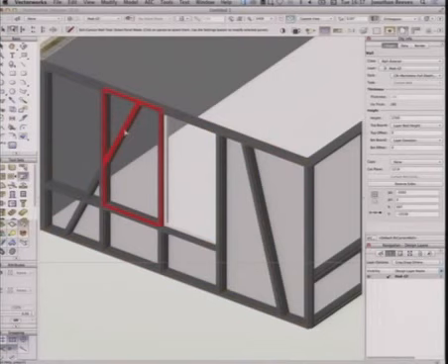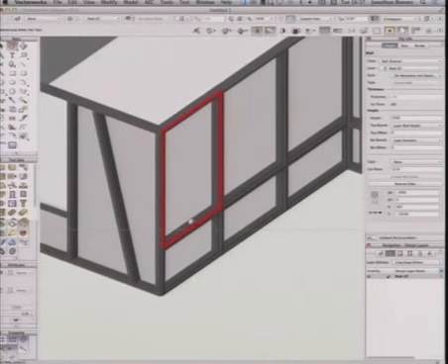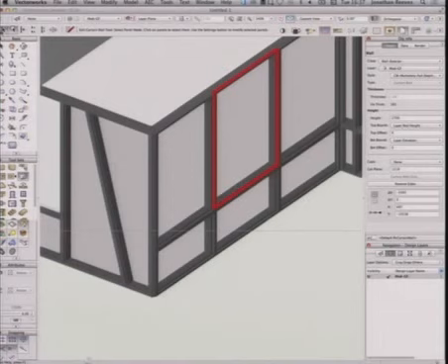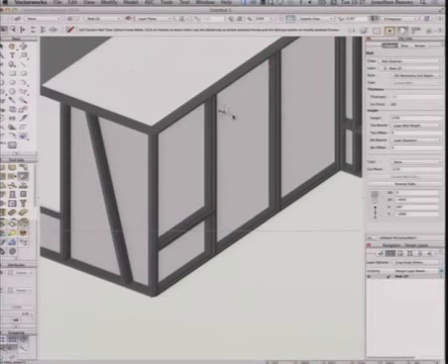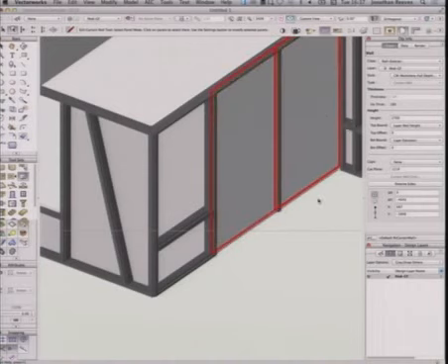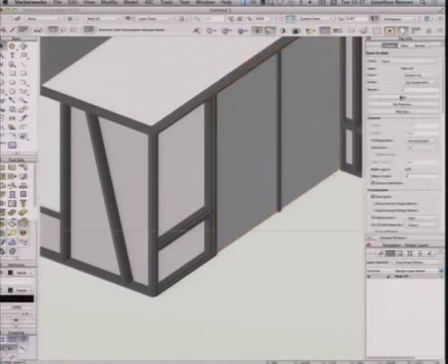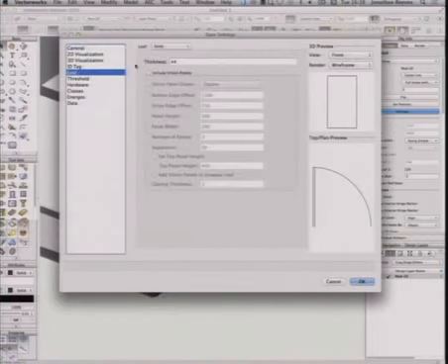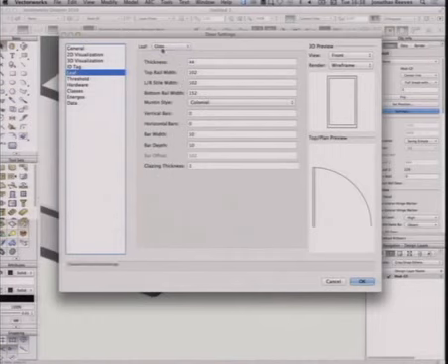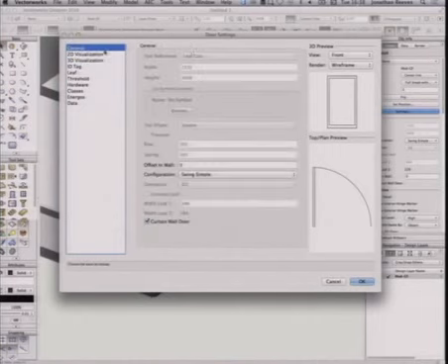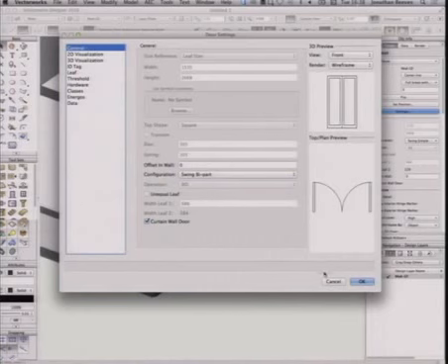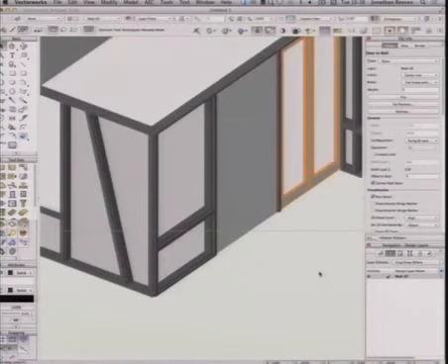Edit curtain wall. So let's go back onto my pick mode, pick the mullion, and back onto the panel mode of the curtain wall. Select those and right-click and insert door. Now that I've got those doors in there, I can easily go into the settings for that particular tool, and all the usual sort of suspects of door and window settings are available. So if I want to make that into a glass door and a set of double doors, you get the idea. Click OK, pretty much sorted.